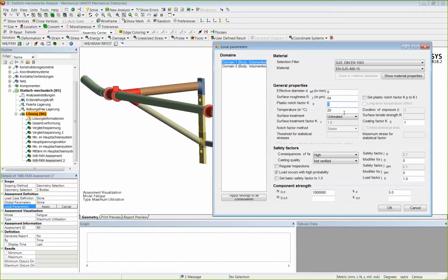I would not recommend that. Or I test till a value where I say, okay, that's the value I need, and I don't need any more. So in this case, I tested against the value of 2. I calculated the force where it plastified at the first point, increased the load by a factor of 2, and saw that my structure was still converging. So I don't know how much I could actually put on, but I could put on more than a factor of 2.